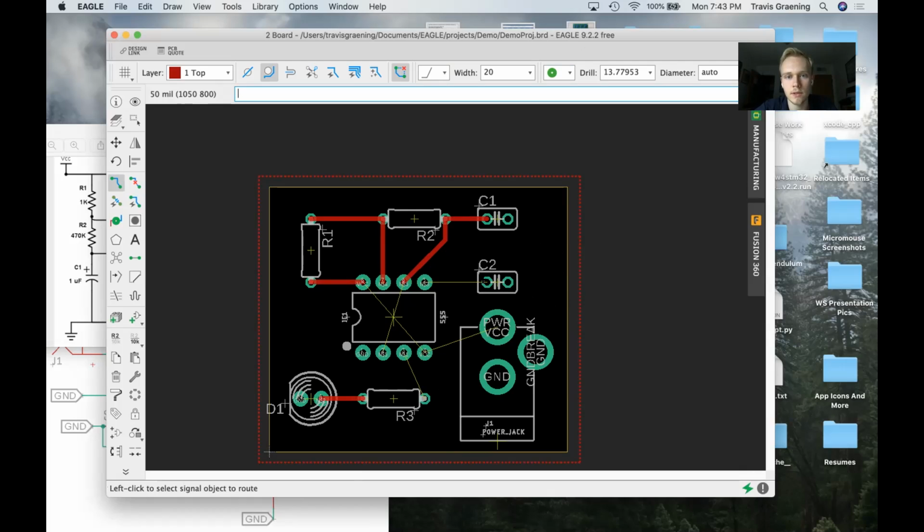All right, so now we're going to, one second. Edit schematic after getting rid of ground wires. You should still be able to move all your components around. I'm just using the move option. I just wouldn't add any new components. So give that another try. Try clicking on move and then finding where the plus sign or the cross is and then moving around.